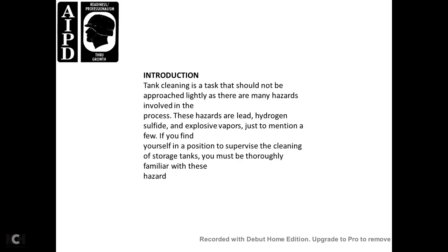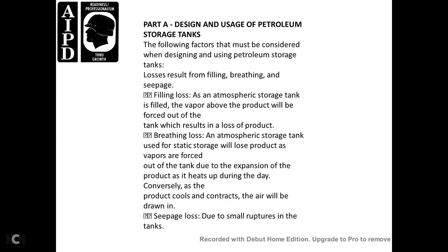Introduction. Tank cleaning is a task that should not be approached lightly, as there are many hazards involved in this process. The hazards include lead, hydrogen sulfide, and explosive vapors, to mention a few. If you find yourself in a position to supervise cleaning of storage tanks, you must be thoroughly familiar with these hazards.